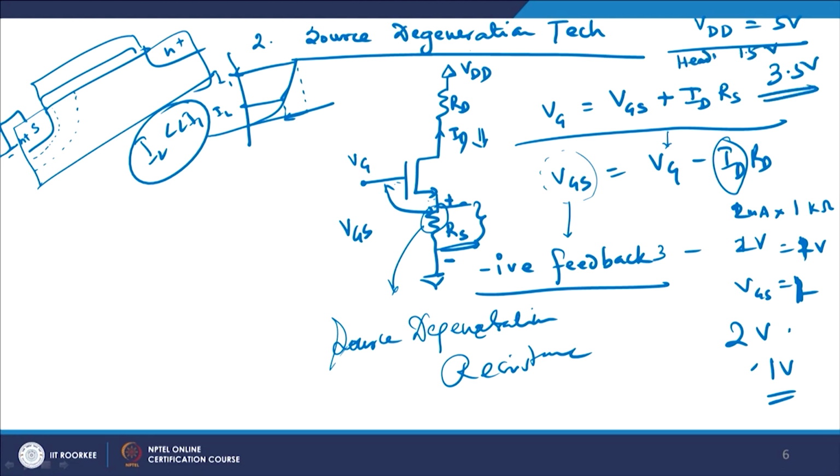This is known as headroom, fine. Also we define legroom. Legroom is when you go to the bottom side. So if you have a current flowing through the device and your bottom should actually be grounded, but you are going to a value, say your maximum value is 1 point something, and the value you are going to is say 0.5, then the legroom available to you is 0.5 volts, and you